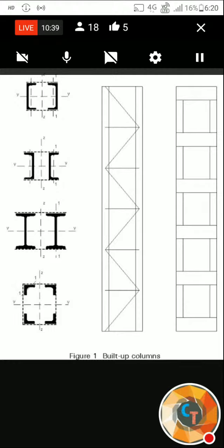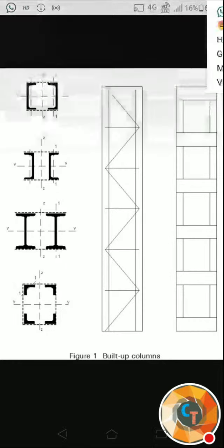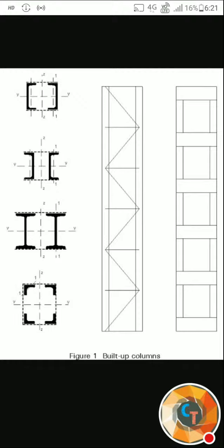I said, sir, on size, you are right, it is on size, correct, but how can you say directly? For example, you take one handful of fine aggregate, that is sand. Can you say which zone it falls in? Which code will you refer to at least? On the basis of mix design? No, you are going to find out the mix design itself. We are designing the mix. Mix design depends on the zone of sand, not the zone of sand on mix design.